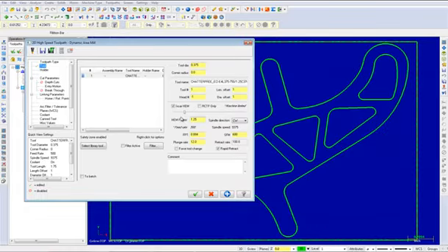HEM factor adjusts the tool's feed rate and spindle speed values to achieve maximum speed and efficiency. Enter a value in the field or use the slider position directly above the field to adjust it. You can enter a value from 1 up to 5, depending on the selected machine and tool configuration. Mastercam displays the corresponding feed rate and spindle speed values below the field. Input the following comment, machine all through pockets. Once the comment has been entered, select the cut parameters.